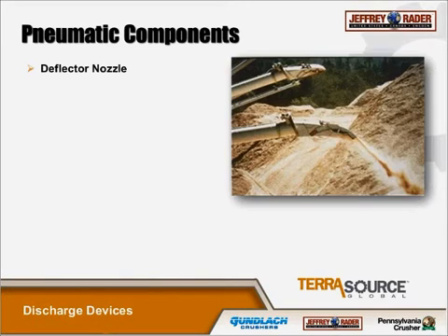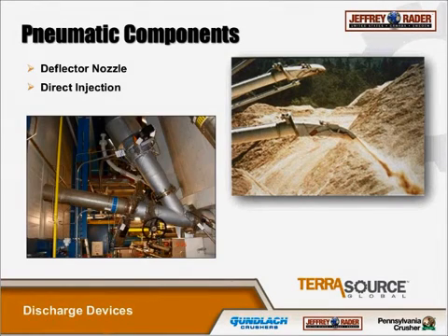Just to finish up the discharge devices, here's a deflector nozzle. Allows you to blow directly into a pile. Creates a pretty big mess if it's sawdust. And here's direct inject. If you're doing a boiler feed, you can directly inject into a boiler. All we need to know is the operating pressure of that boiler, and we're good to go.